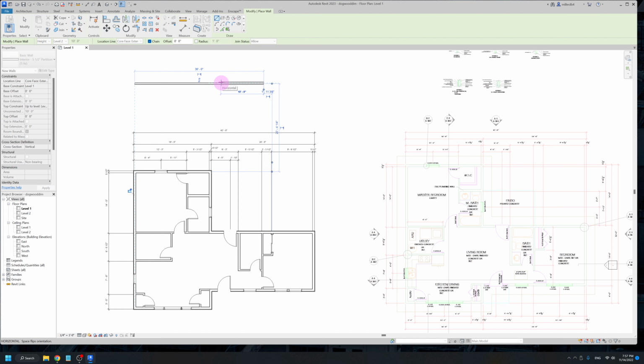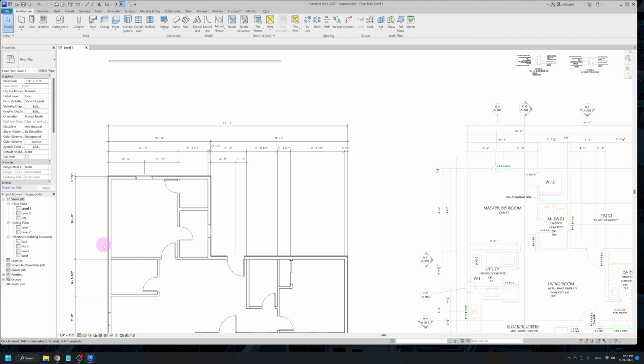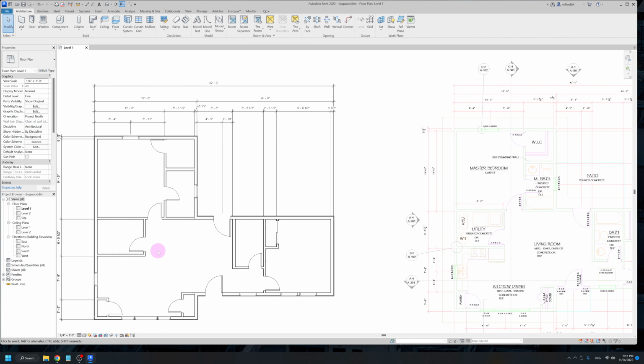So you can have it kind of go dimension as you go, or you can then just make your general shape and add dimensions after the fact. And as long as you're keeping your numbers relatively friendly, up to like 1/2 inches, sometimes 1/4 of an inch, then you're going to be in a good place. But what you don't want to do is leave any of these numbers or these measurements to be like 30 seconds or things like that, because then every contractor is going to hate your guts.